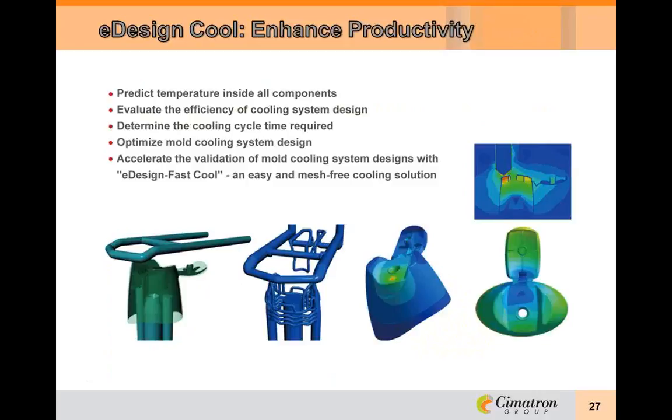eDesign Cool, with its true 3D analytical core, can accurately analyze the mold temperature, the efficiency of cooling channel layout, and the required cooling time in the design phase. It is a useful tool to detect potential defects in the mold cooling system, such as unbalanced cooling, hot spots, and prolonged cooling time due to poor cooling efficiency. You can accurately evaluate the cooling efficiency to further optimize the cooling system and reduce cycle time.